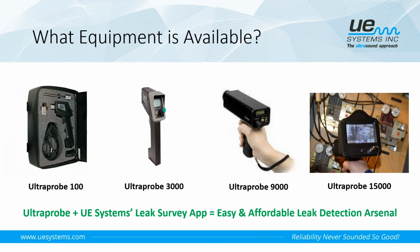Then move over to the right to the UltraProbe 3000. Now, this model here, we specifically came out with several years ago for energy applications, so compressed air leak detection and steam trap inspection. Similar in size to the UltraProbe 100, but unlike the 100, which is an analog instrument, the 3000 will provide you a true decibel level number on the display. So we'll see how that true decibel level number is important when we get to how we quantify and calculate how much a compressed air leak is costing. So you'll need an instrument that will give you a digital readout for that.